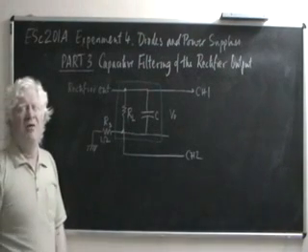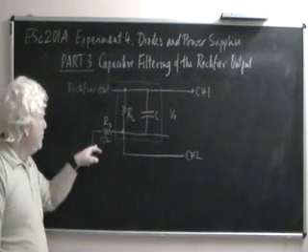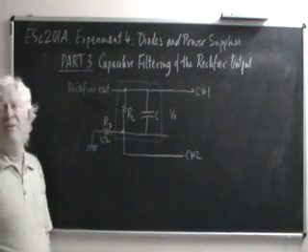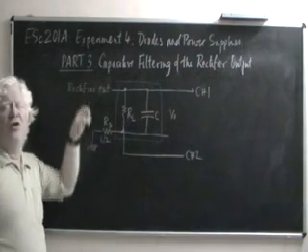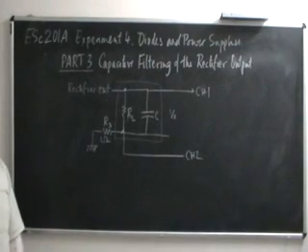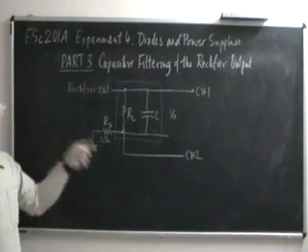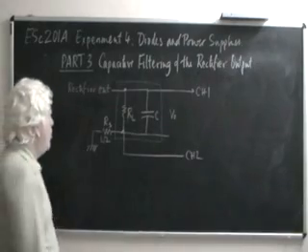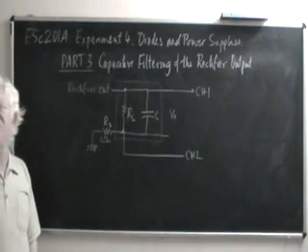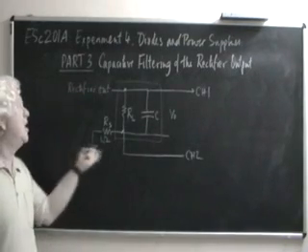The last time we were trying to measure current, when we were trying to plot the diode characteristics, we put the series resistance meant for voltage measurement on the source side, not on the ground side. And therefore, measuring the current by using the proportionate voltage developed across the resistor required a difference amplifier. Here we don't need to do that, because one end of Rs is already at ground, so channel 2 that's connected to this will directly give you the voltage across Rs with respect to the ground, and that voltage will be proportional to the current that's passing through.